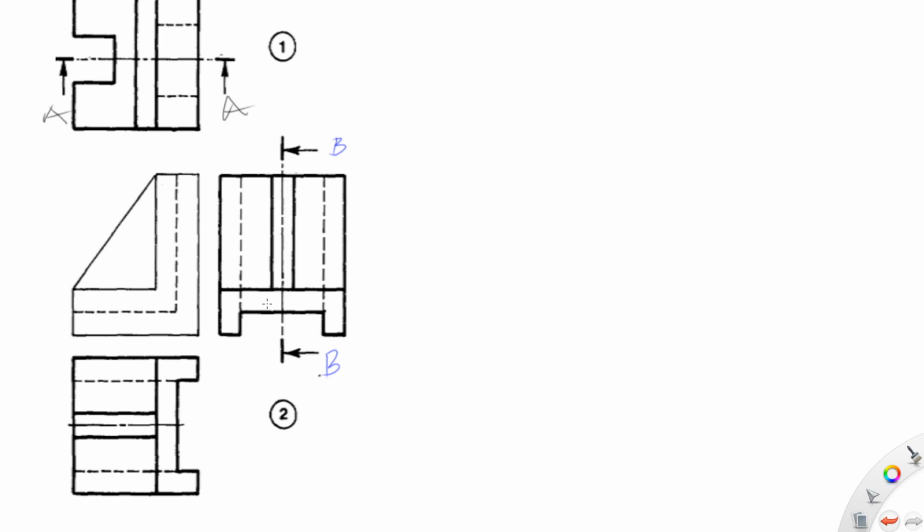section webs. So here, if we are to provide a sectional front view, again, if you look at the cutting plane, it has gone through the center of this member, so it will reveal all the hidden features. So on the front view, this line which is appearing as short dashes will have to become continuous.